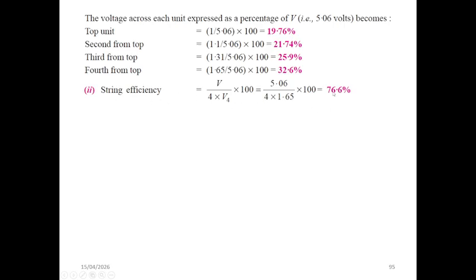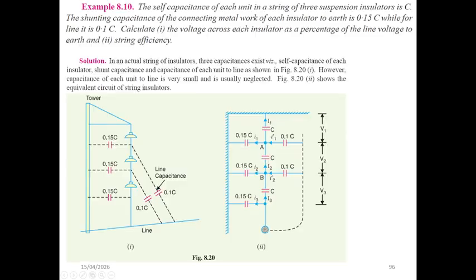So string efficiency will be equal to 76.6%. This result indicates that the string is not fully efficient, as the voltage is non-uniformly distributed and the lower units are subject to higher electrical stress.